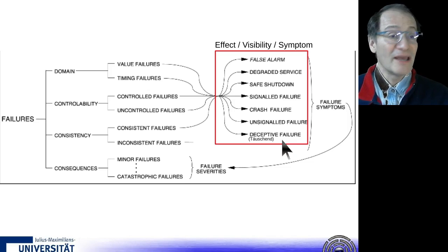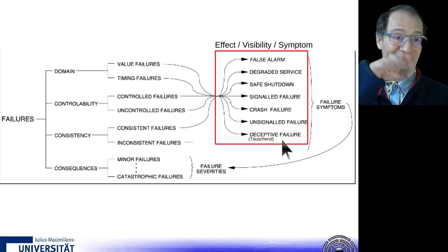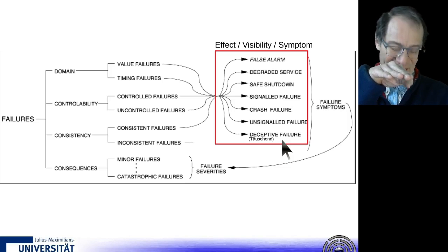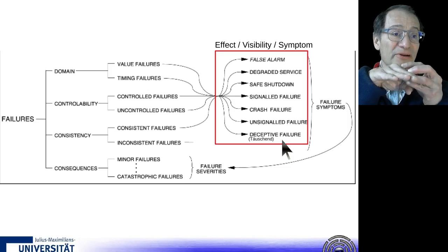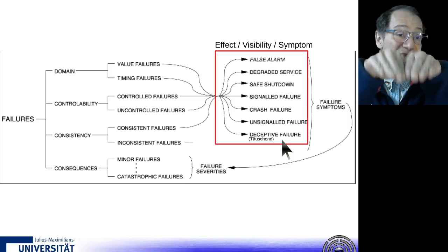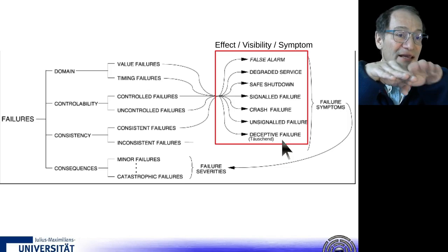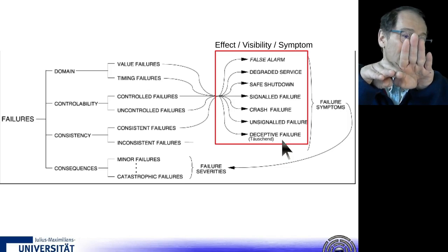A very common case is the angle of attack. So you can see how the aeroplane is flying. Several times the case has been that it is frozen, it doesn't move anymore. So even if the aeroplane is changing its angle of attack, this device will continue reporting you are flying, for example, horizontally, even if the aeroplane has an angle of attack like this, or a pitch angle like this.